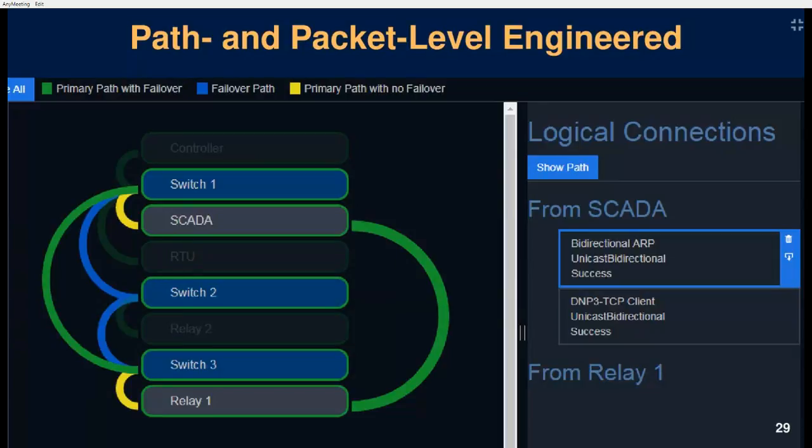On the left-hand side, it shows that there are single points of failure with only having this device connected to the switch one time. What we typically see in energy control systems is a backup, which could be serial communication, or you might have another Ethernet port connected to a parallel redundant path to another separate network, depending on the level of importance of that substation.